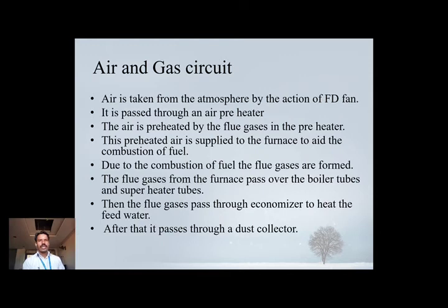And then the air passes through the preheater. The air is heated by the exhaust gas, or flue gas, sent out by the boiler. With the help of that heat, we can utilize it. The air is preheated by the flue gas in the preheater, and the preheated air is supplied to the furnace to aid the combustion of fuel.